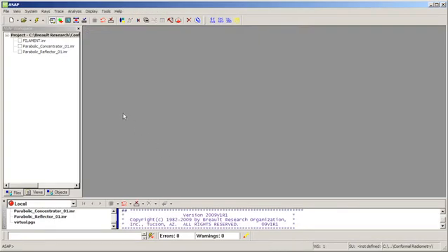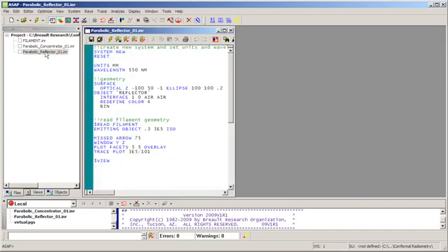We'll illustrate the feature with an example using a parabolic reflector and a filament source. The conformal radiometry feature can be invoked with a simple addition of the keyword bin to any surface or edge object within our optical system.